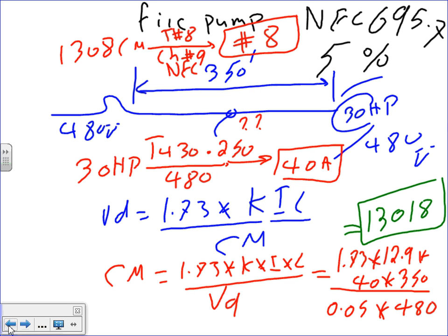That's a real situation. This is an easy calculation if you know that your load is located in one area, summed in one area, and your source is in another area, with a distance in between. If your load is scattered, as in parking lot lights, you're going to do a voltage drop on parking lot lights. Which light are you going to go to? Each one of them is probably 50, 60, 100 feet away from the other, right? Which one are you going to take? The one that's 50 feet away from the source, or the one at the end of the line, which is 500 feet away from the source? We're going to do this next week. But if the load is summed in one area, no problem. The calculation is really easy.